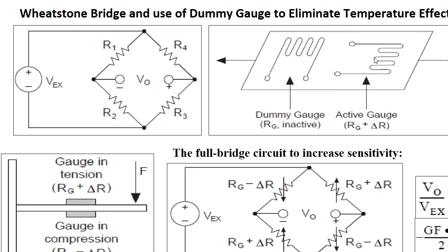two gauges are used, one on top and the other one on bottom. So this one is on top, this one is bottom, and these two strain gauges are oriented along the direction of the stress. These two are considered for the first part of the experiment to determine the Young's modulus. And in the second part,